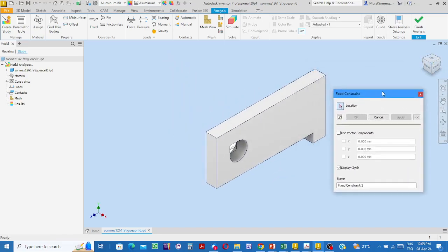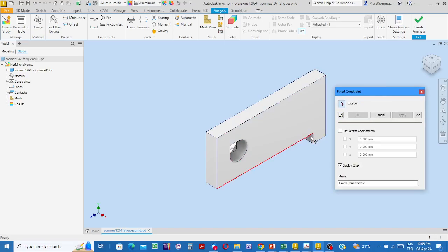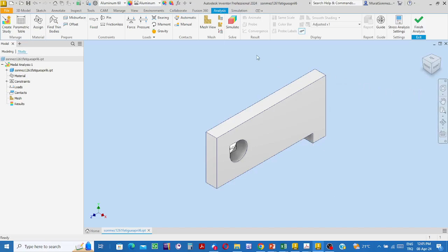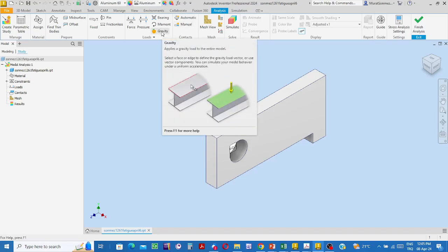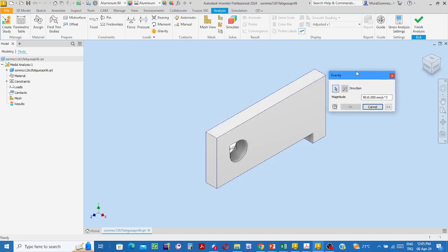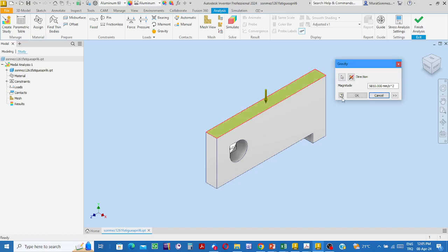And for finding the resonance frequencies, in the equation we have stiffness and equivalent mass. Stiffness is fixed via selecting the material. For aluminum alloy, there is a corresponding elasticity. To be able to say that the mass is also an effective term, just indicate where the earth is. Gravity, click on this, and then indicate one of the surfaces.